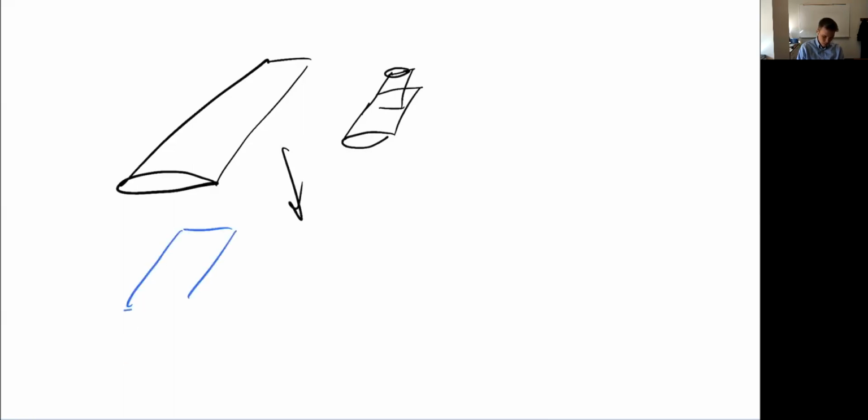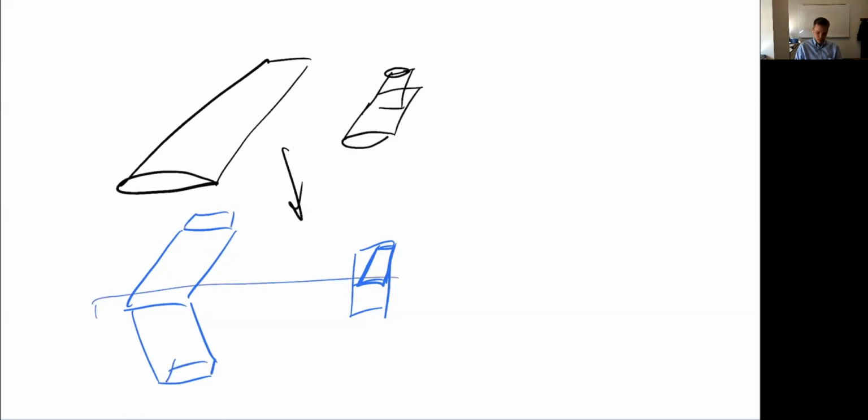Let's say I've got a swept wing here, and I've got this tail and a vertical tail, but I'm going to keep the same planform areas and shapes and sweep and all of that. I'm going to flatten them like we would in thin airfoil theory. I'll still try to use appropriate boundary conditions, accounting for the twist on the sections and the dihedral, so I can have winglets. Let's add some winglets here on this wing. Sometimes people will add a flat section for a fuselage, kind of a sideways one, and if you want to get yawing moments, for example, it may be important, but we're going to really focus here on lift and induced drag.